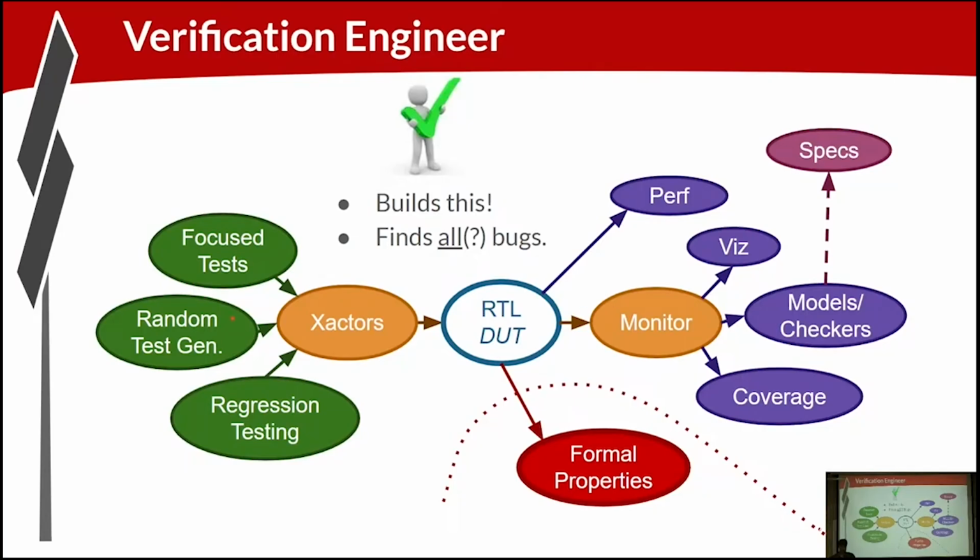And in addition to all this, so this would be dynamic verification or functional verification that's based on simulation. We also have formal verification, which is a more mathematical, proof-oriented verification to prove properties about the design. Prove them 100%, for all scenarios, not just for particular simulations with particular stimulus.